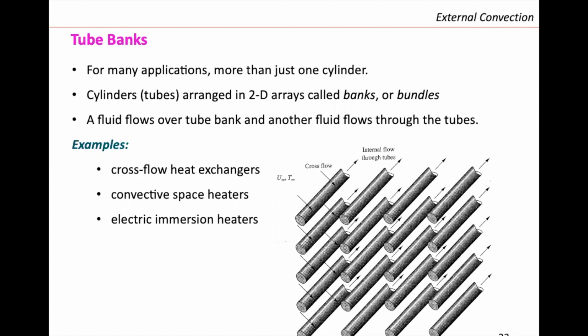So again, we are putting several tubes together. As you can imagine, now that we have a 2D arrangement or bundle, everything changes, right? The temperature profile will change, the velocity profiles will change, because you cannot evaluate only one tube. All of them are interacting, so there will be different profiles along the columns or the rows of the bundle.